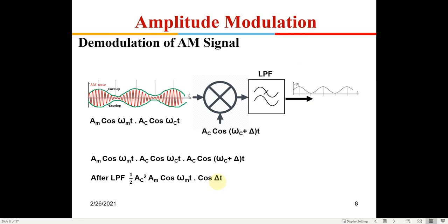Because you have a transmitter which is continuously transmitting. Say on the transmitting side you have a carrier of 120 megahertz. That may not transmit exactly at 120 megahertz. Even with time it might change to 120.001, 120.002, and with temperature and things like that, it will slightly keep varying. Similarly, on the receiver side, the local oscillator will also have small oscillations within the tune.